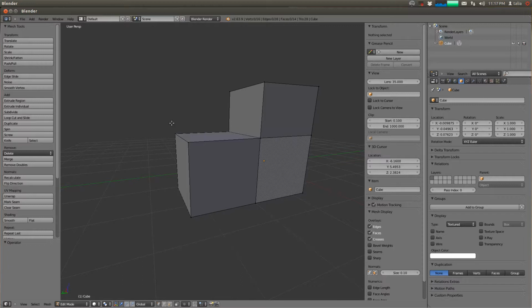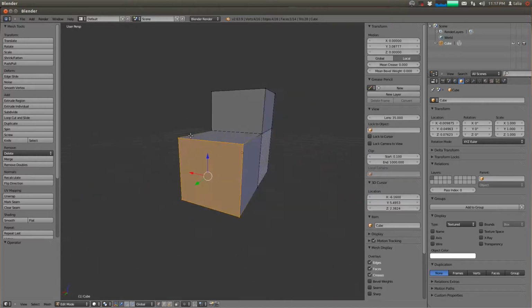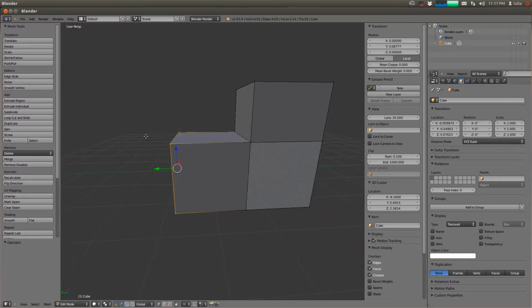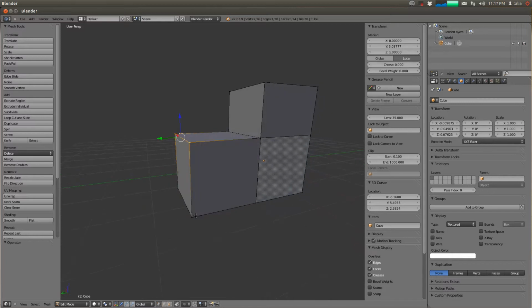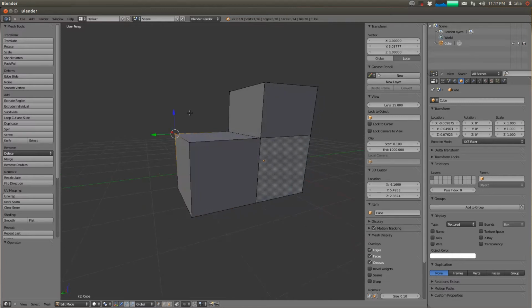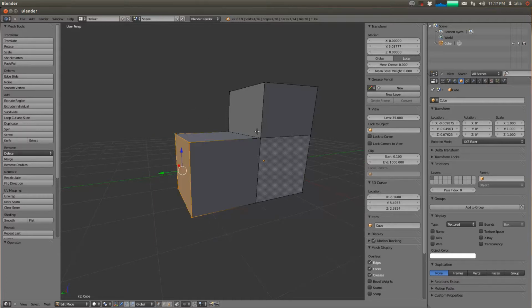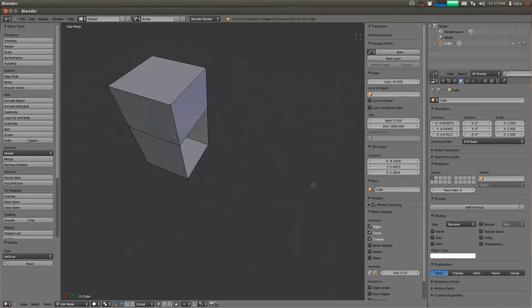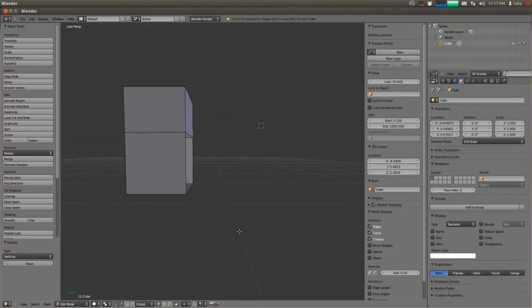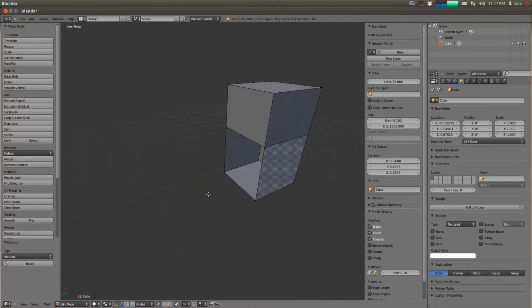I'm going to hold down Control and left click and drag, and that's going to draw a selection box. Then I can grab all 4 of these in a much simpler method than having to go through and manually click them. So, useful trick, remember that: hold Control, left click and drag. And then I've selected all those. So actually what I'm going to do here is hit X and delete all of these vertices. And now I've removed that whole section of 5 faces and the attached edges and vertices that were coming off of those vertices.